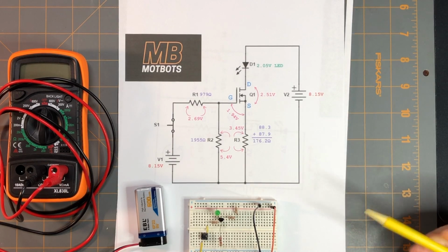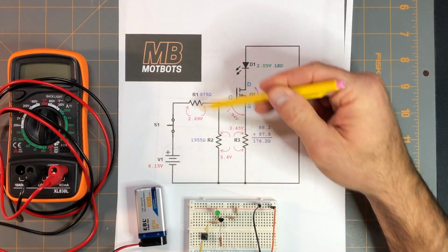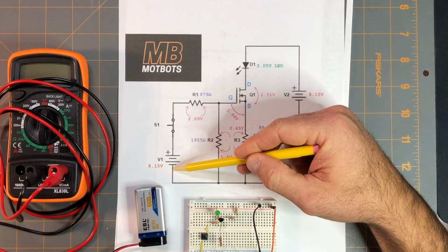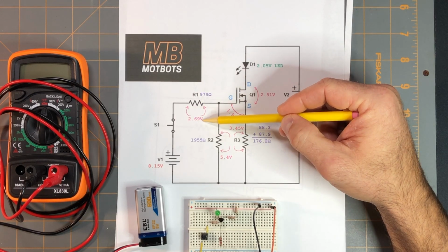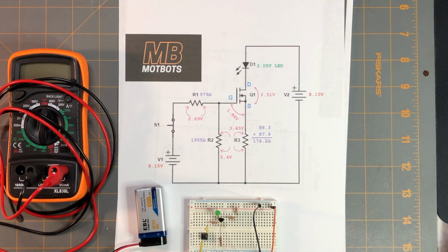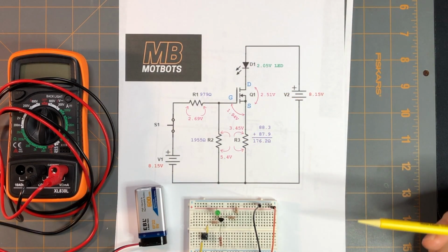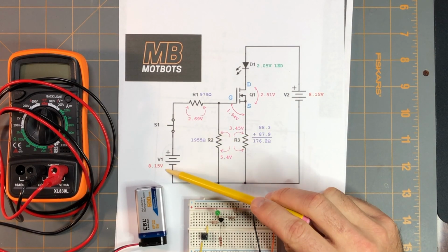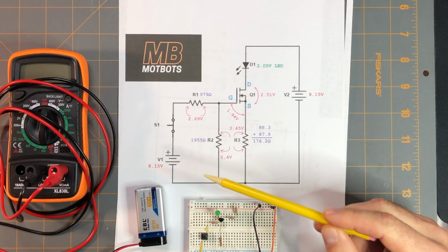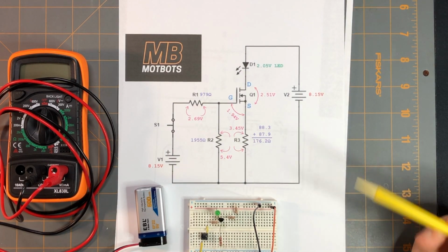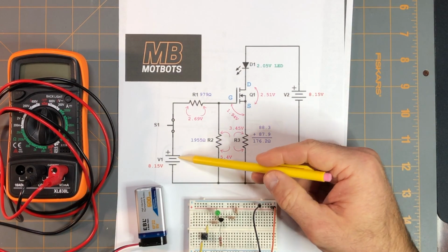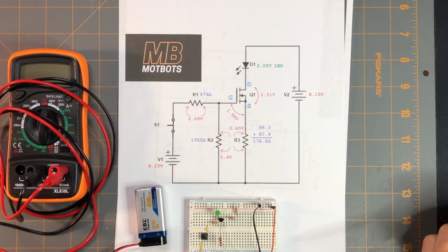And again, using Kirchhoff's voltage law, the sum of the voltage drops across these two resistors should equal the source voltage of 8.15 volts. And if I add 2.69 volts plus 5.4 volts, I end up getting a voltage value of 8.09 volts, which is, again, pretty darn close to this 8.15 volts. And again, we might need to consider some voltage losses within this part of the circuit, again, the internal resistance of the battery source, so there's that.